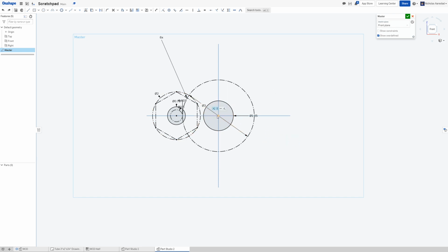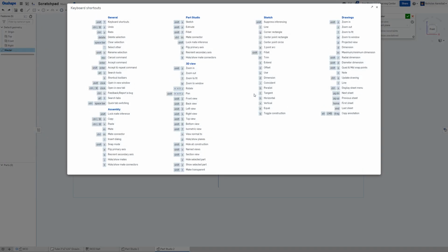So you can click those and delete those whenever you want, right? Sometimes that's really useful. I'll talk about a situation where that's really useful later in this video. Onshape, you've been noticing I've been doing a lot of hotkeys. Onshape has a really great hotkey menu that you can open up. Always check these. So I just did Shift question mark. That'll open up this hotkey menu, right? And you can always check what hotkeys you could use if you forget them.